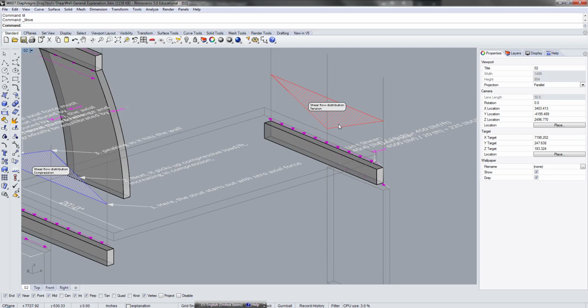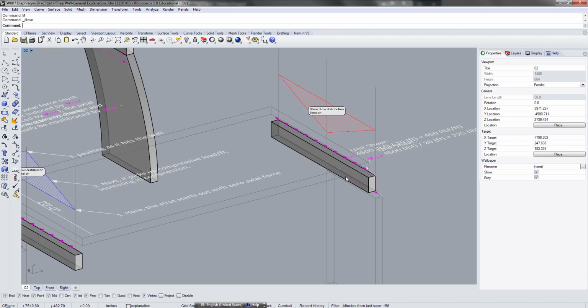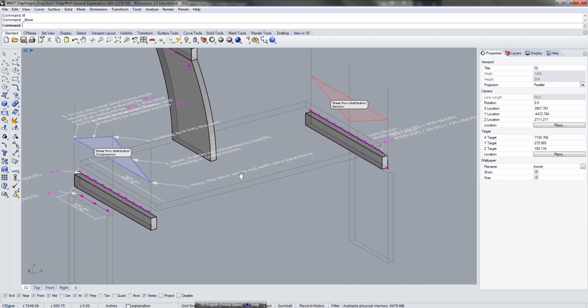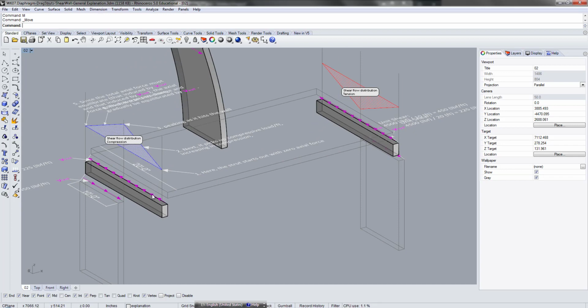Okay, so what's happening here is that unit shear on the shear wall side was greater, right? If you remember, it was double, right? Because the length is half, right? So the unit shear on that side is double. So you have more force pushing against you in this direction than that direction. So in comparison to the previous one, here you only had a force that's going this way.